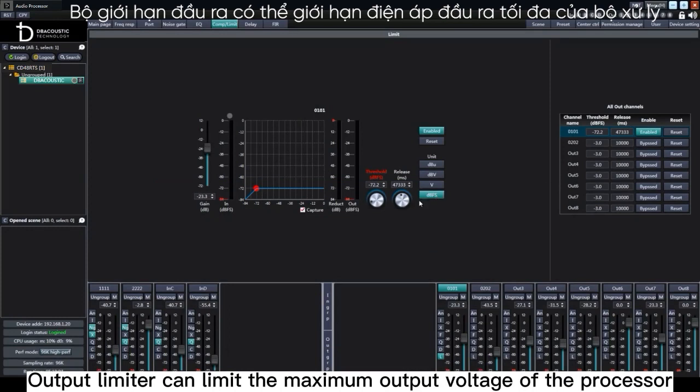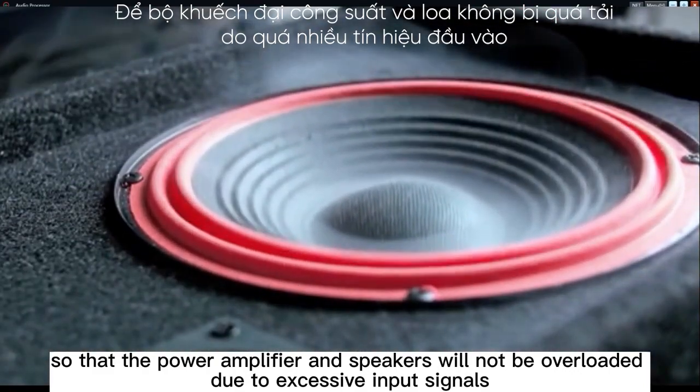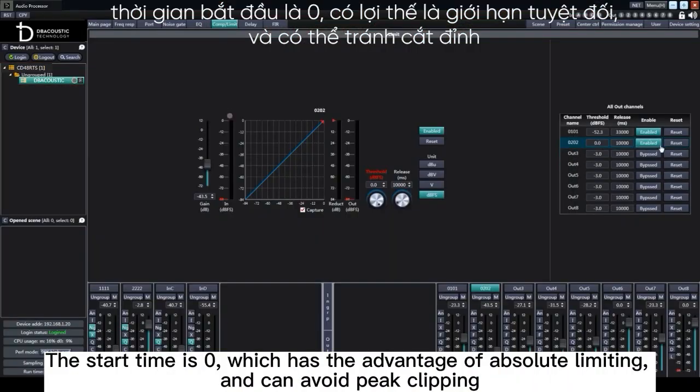Output limiter can limit the maximum output voltage of the processor, so that the power amplifier and speakers will not be overloaded due to excessive input signals, thereby protecting the power amplifier and speakers. Our processor uses a brick wall limiter. The start time is 0, which has the advantage of absolute limiting and can avoid peak clipping.